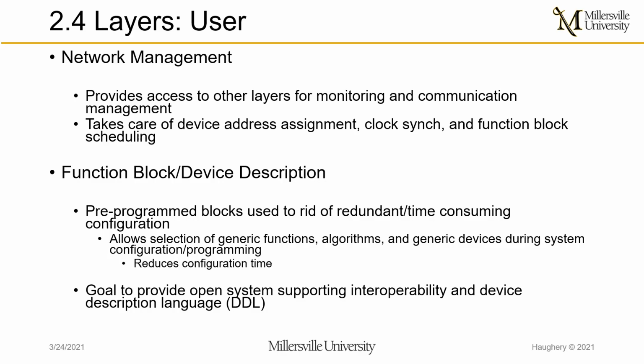The function block allows for pre-programmed blocks used to rid of redundant and time-consuming configuration. This allows for selection of generic functions, algorithms, and generic devices during system configuration programming. This inevitably just reduces the amount of time the user has to configure the Fieldbus network.